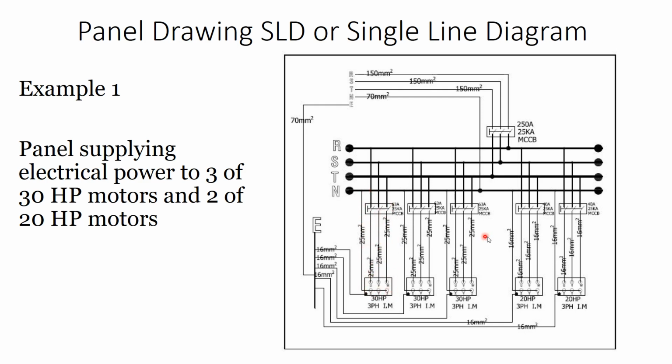Similar to this, the other motors, you will find here 3 phases R, S, T and the neutral. So we have the bus bar connecting between the incoming and outgoing. Now the most important thing is the earthing here. You will find that the earthing here has a similar cross-sectional area to this incoming neutral, 70 millimeter square. Now this is the earthing bus bar.